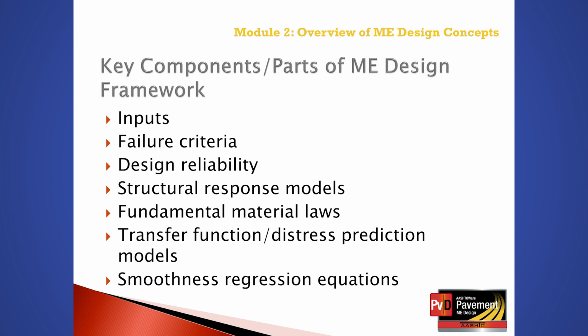In summary, the key components include the inputs to the PMED software, the failure criteria for each distress type for specific pavement design strategies, the design reliability for the pavement design, the structural response models, the fundamental material laws, the transfer functions, and distress prediction models based on Miner's hypothesis for calculating damage, and the smoothness or roughness determined by IRI regression equations.